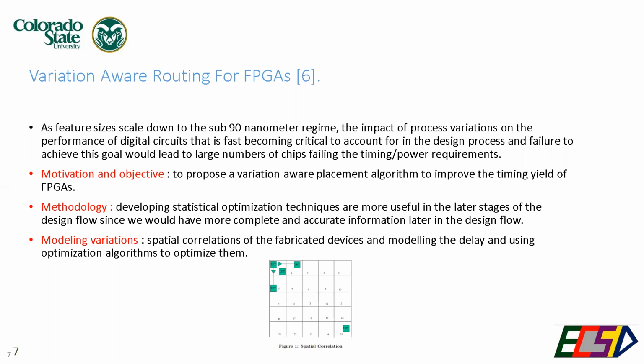The most important motivation behind this is to propose a variation-aware placement algorithm to improve the timing yield of FPGAs, based on developing statistical optimization techniques and by modeling the variations that we have in the circuits, both intra-die and inter-die, in the ICs.